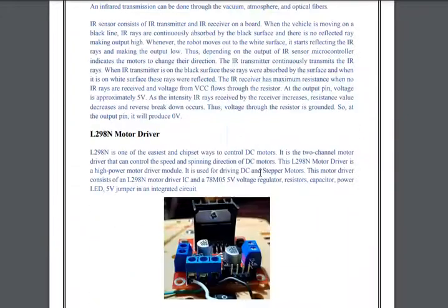After that, this is the L298 motor driver. This is the L298 IC. These are some capacitors and voltage regulators. It has 3 pins. This is the 12 volt input pin, the center pin is the ground pin, and this pin is the output 5 volt.